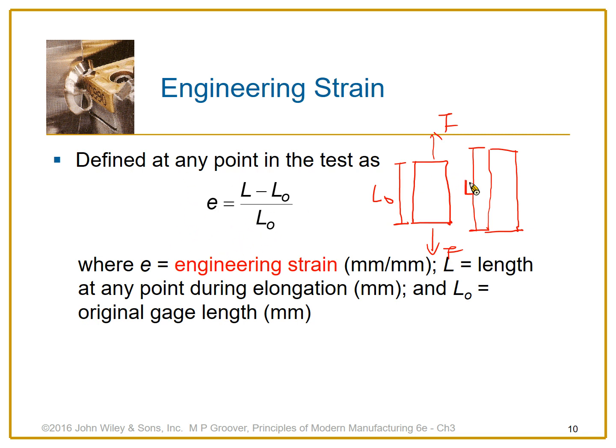So that is how we calculate it. After we finish the testing, the length L minus L0, divided by L0. So it's like a percentage, right? And this term we call the engineering strain. We use this to define the trend, how the specimen changes in terms of size.